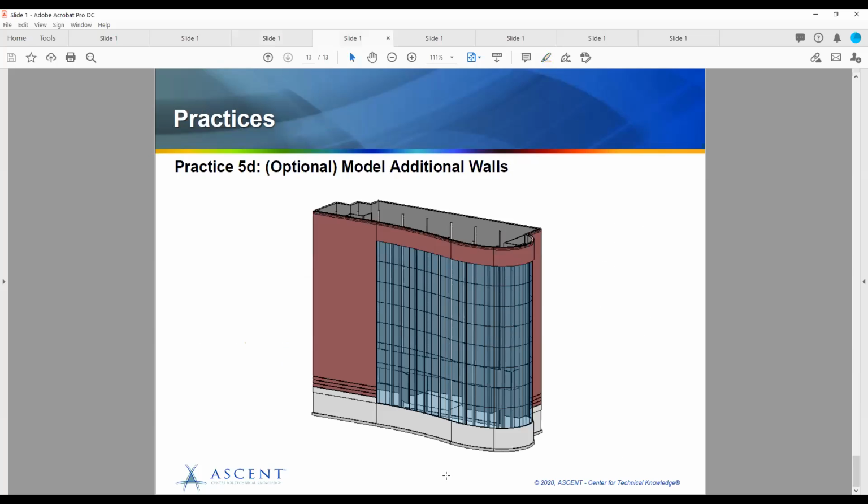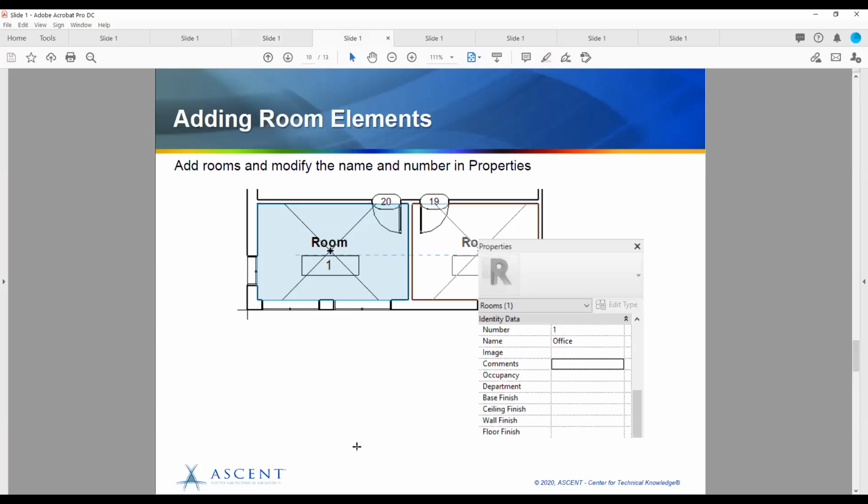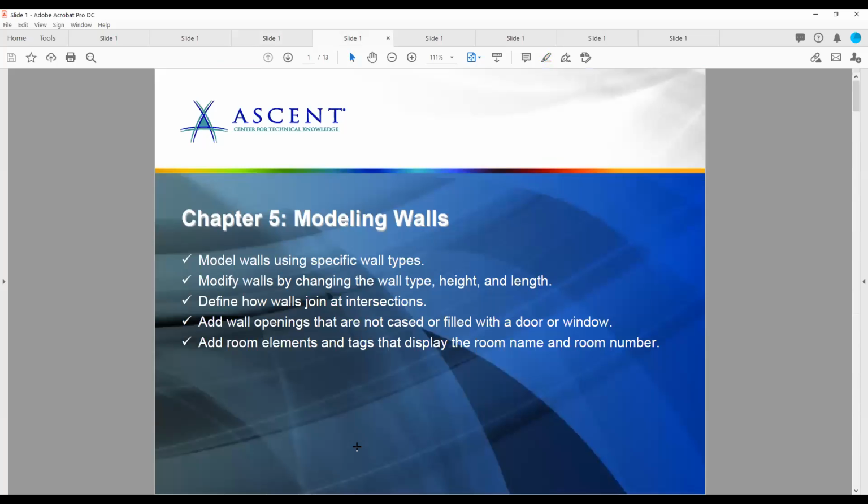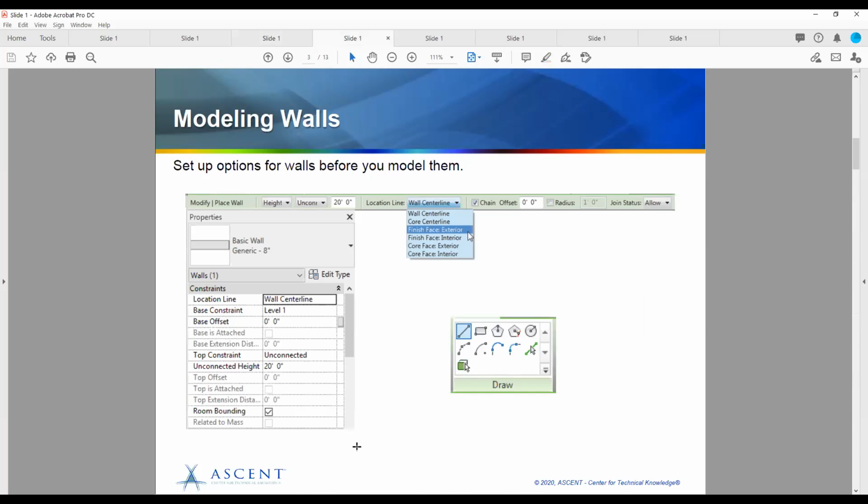Okay, going into here right now, the next thing we talked about, we did talk about walls last week. We did some wall exercises, and one of the things we talked about was how we could draw the walls. One thing that is important to always remember is that walls are to Revit as lines are to AutoCAD. In the same way you use lines to draw everything in AutoCAD, that's what you're going to do with the walls command in Revit.